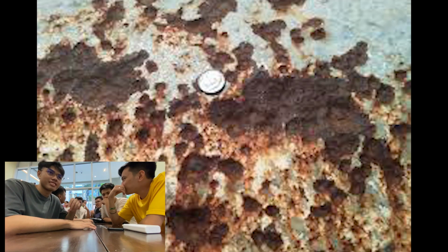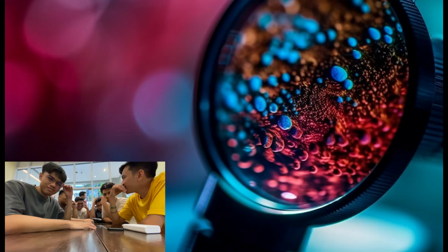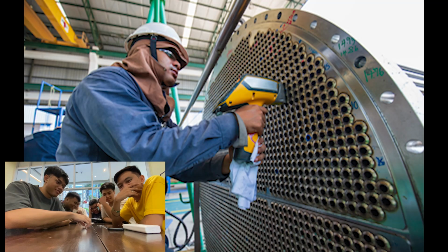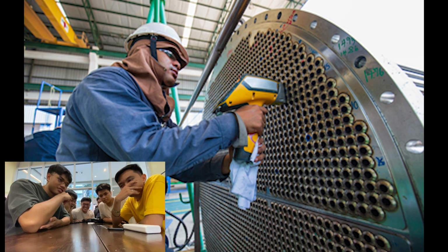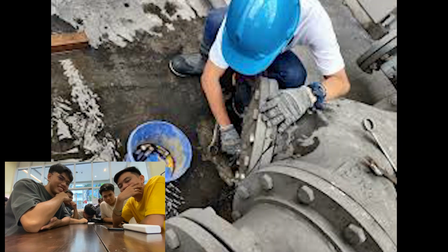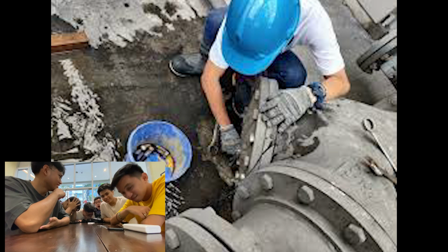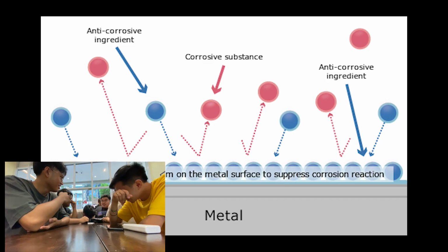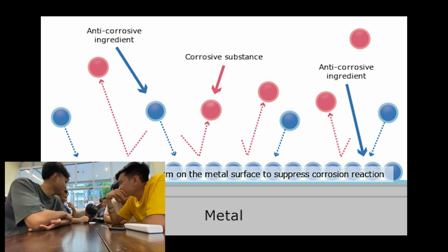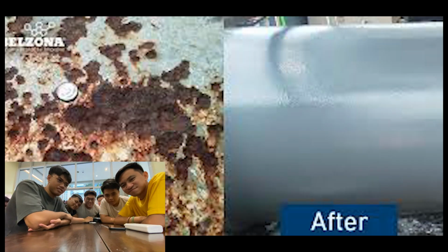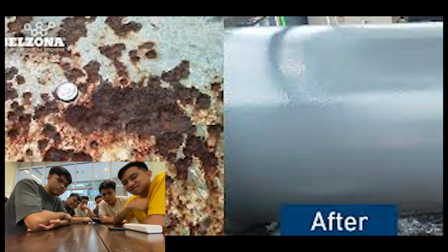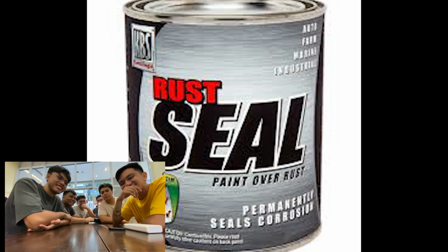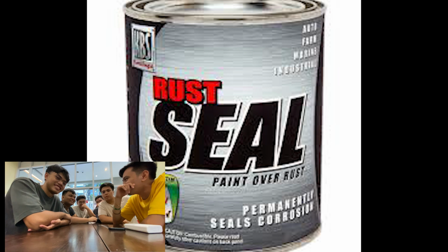Pitting corrosion. Treatment. 1. Detection. Use non-destructive testing, NDT, methods such as ultrasonic testing to detect pits. 2. Mechanical cleaning. Employ fine abrasive pads or brushes to clean the affected area. 3. Chemical cleaning. Use a mild acid solution to clean the pits thoroughly. 4. Filling. For deeper pits, apply a filler material compatible with the aircraft's metal. 5. Sealing. Seal the area with a corrosion-resistant primer and topcoat.